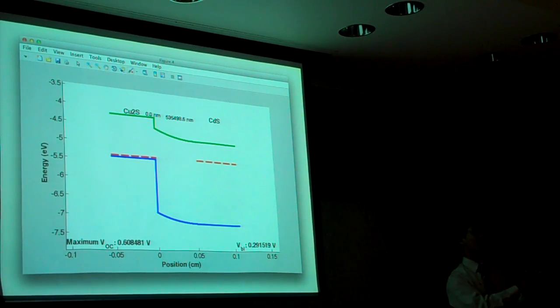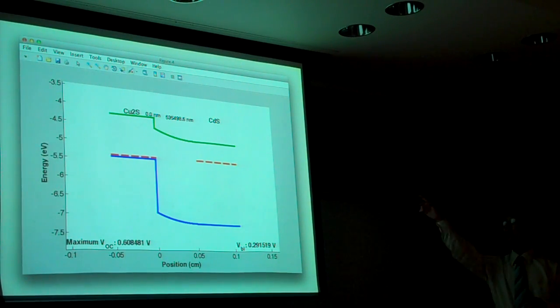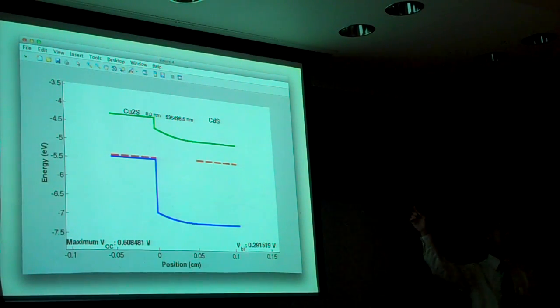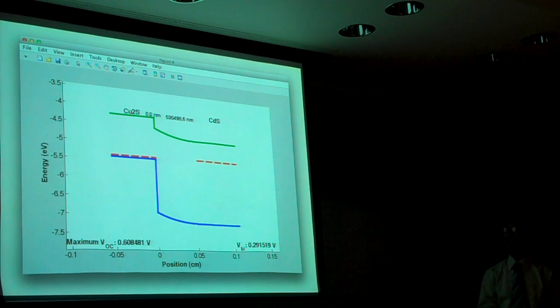So it takes a lot more distance to get the same number of electrons when we compare it to the copper sulfide, which is very, very dense. So it doesn't take a lot of distance. And actually, the two numbers at the top are the depletion widths on both sides of the junction, and the one on the side of the copper sulfide is not 0 nanometers, it's just too small, and it got rounded away.